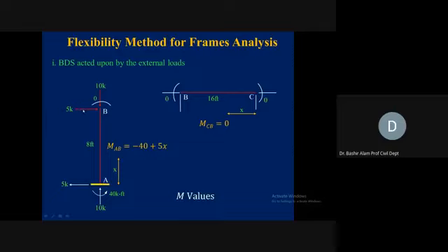So this 5 kip externally applied load is rightward, so summation of Fx will give you 5 kip leftward directed here. This 10 kip is downward, so 10 kip in the upward direction. Let's look at the moment now. So 5 times 8 is giving us 40 clockwise, so 40 counterclockwise. This is the support reaction at joint A.